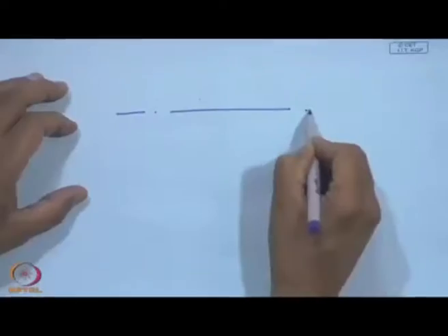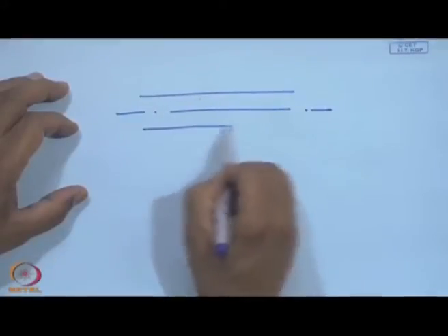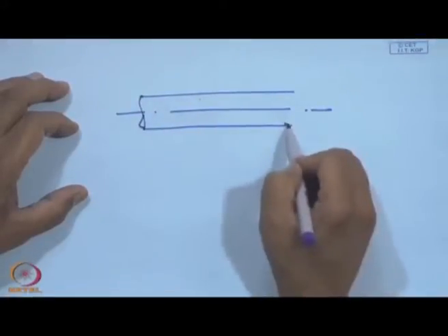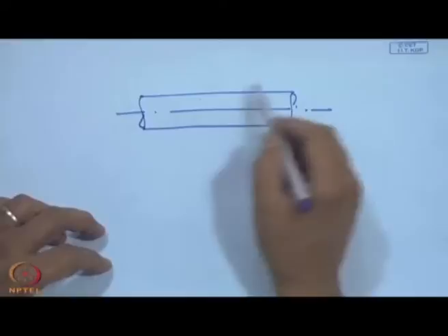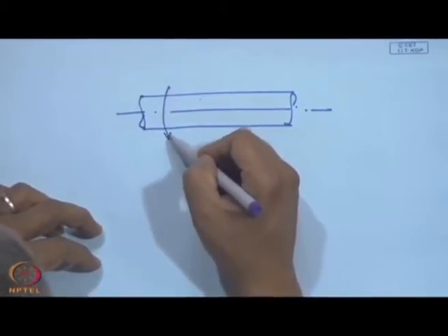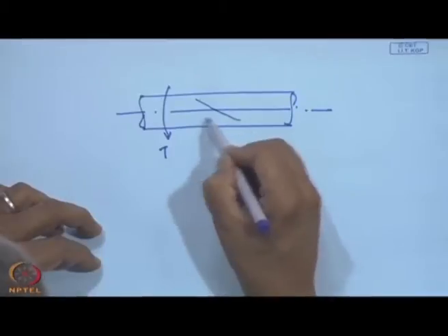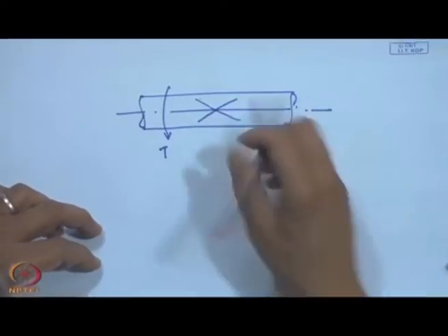Okay. This is a type of crack, which is known as the transverse crack because of the flexural loading on the shaft. Okay. Another important thing happens actually, as you know, the shafts usually carry torsional loads. They transmit power, so they carry a lot of torque. And usually, because of the torque, the maximum shear stress occurs along the 45-degree lines. Okay, if you are transmitting torque, usually the cracks are at this 45-degree axis and somewhere here.